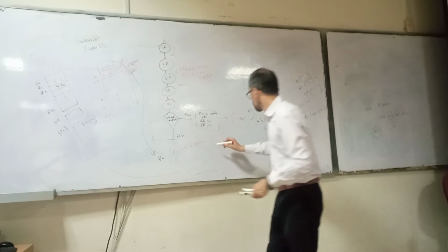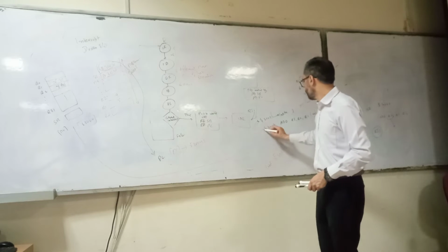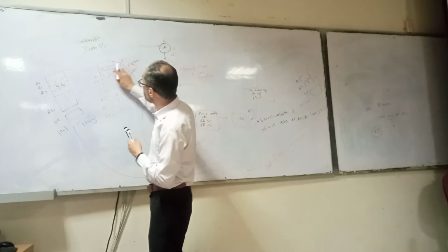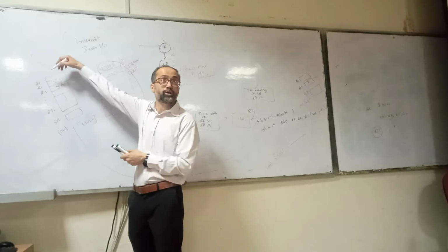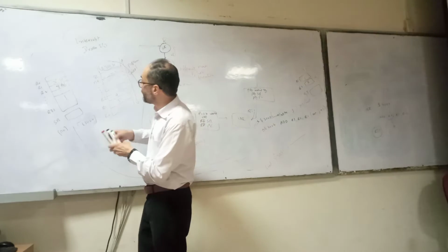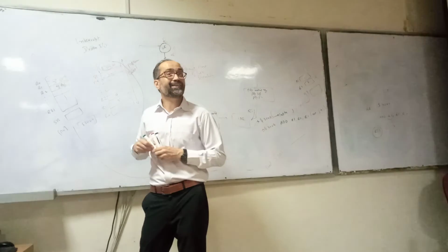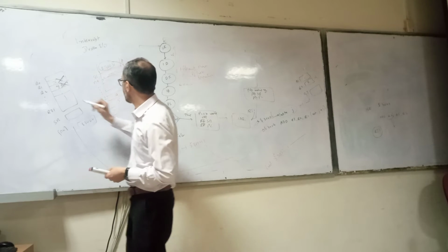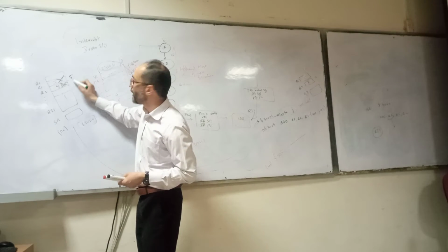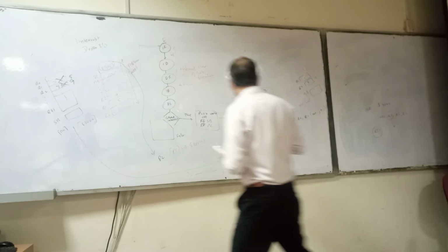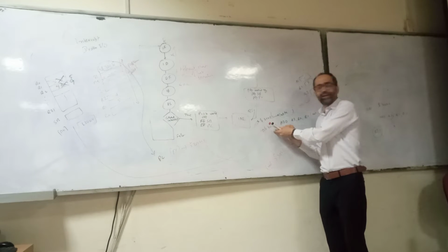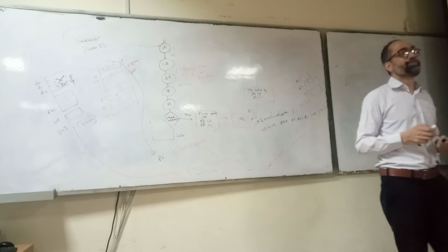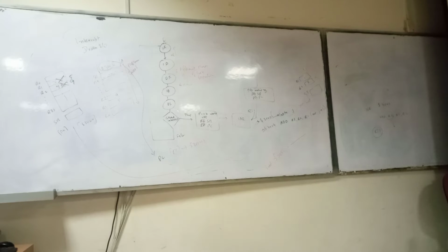So now what is the value of the program counter? $3004. To which instruction is it pointing? J plus 1. This. And then all these values that were pushed on the stack will be restored to the working registers. So now, even if the working registers are modified by the subroutine, their old values will be resumed. What are the old values? 5 and 9. When the program is here, it will see 5 and 9. So in this case, will the program be consistent or inconsistent? Consistent.